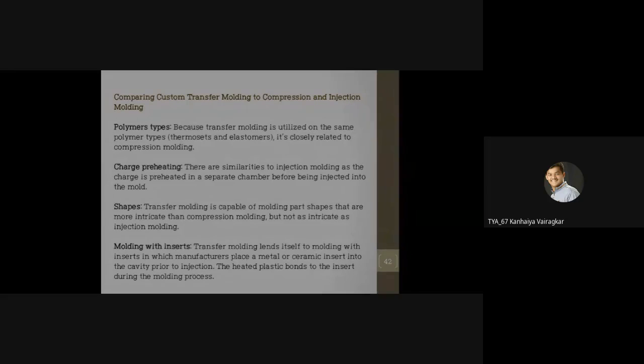Same process here. There is a preheating inside the transfer pot, and then the preheated material is pushed by the plunger into the cavity. Okay, so this preheating is the major difference between the compression molding and the transfer molding, but it is similar to the injection molding.